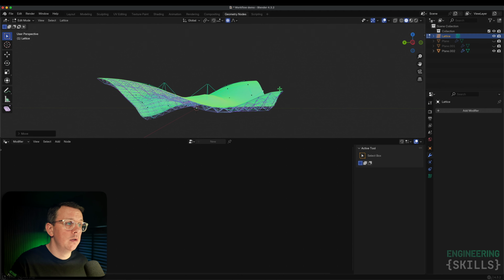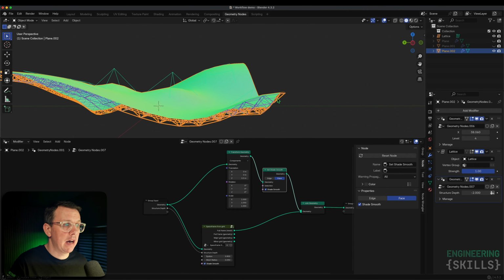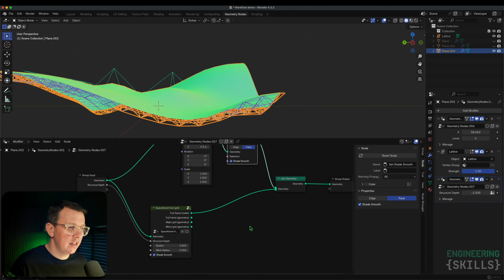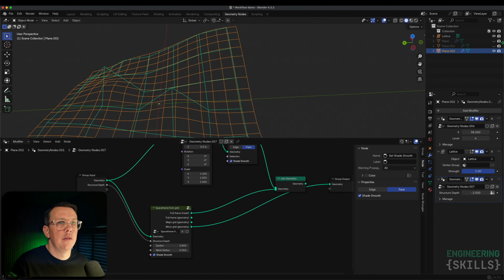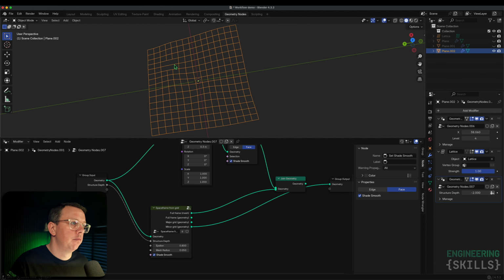Always make sure though, once you've done that, to tab out of edit mode on the lattice, go back into the structure and double check. If you're using this implementation, which I still hope to improve, you've got to make sure that the minor grid is a full grid. So let me hide the lattice and we can see, no, we've broken our grid. So let's change our tuning parameter, try increasing it. Excellent. Now we could proceed with an analysis.